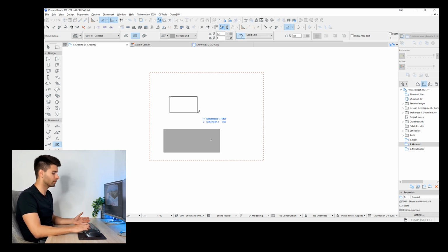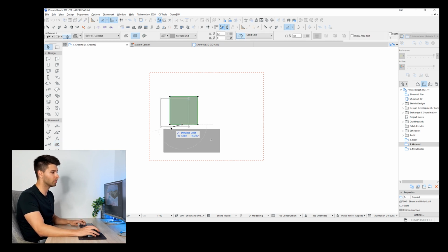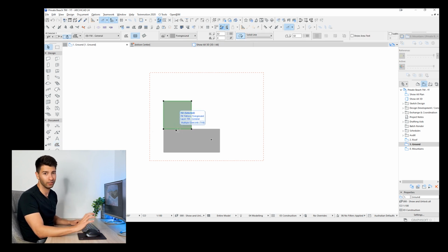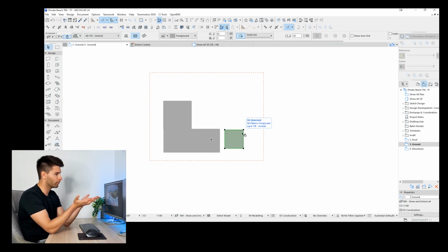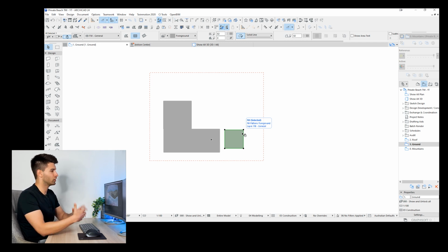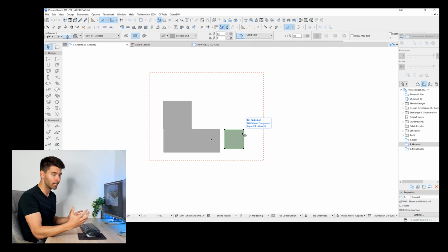We're going to have some sort of parking, so a 6x6 garage is pretty typical to be able to actually facilitate 2 cars in the actual property. And then we want to have at least 1 bedroom, and a master bedroom is anywhere from 4 meters to 5 meters. In this instance, I'm going to pick 4 meters by 4 meters and then start manipulating the shapes, messing around with them like a Tetris game to actually be able to create something phenomenal.